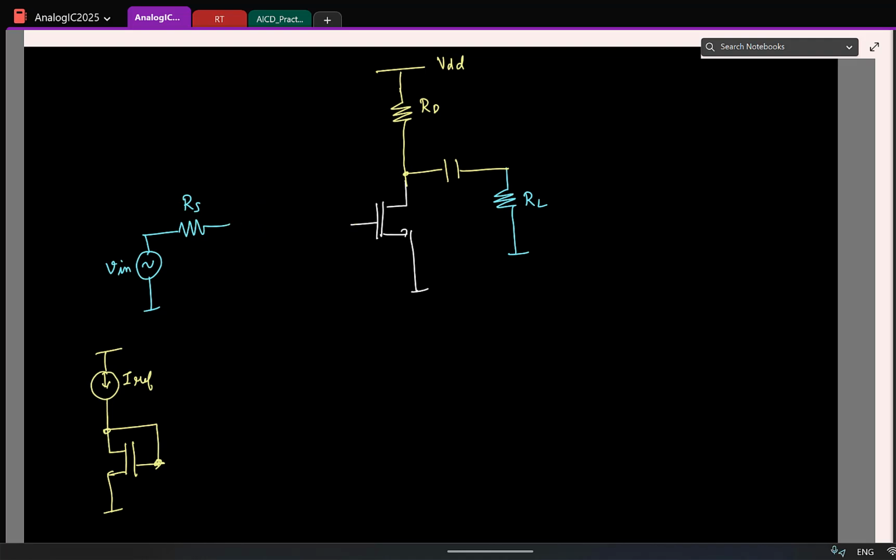Great. So let me replace it with a capacitor. And remember, this capacitor has to be charged to this voltage. So what do you do now? Should I connect it directly, or what do I do? Again, I have to have a resistance. I'll call this RB. So this way the capacitor is charged to that required voltage, so that the DC shifting is done.